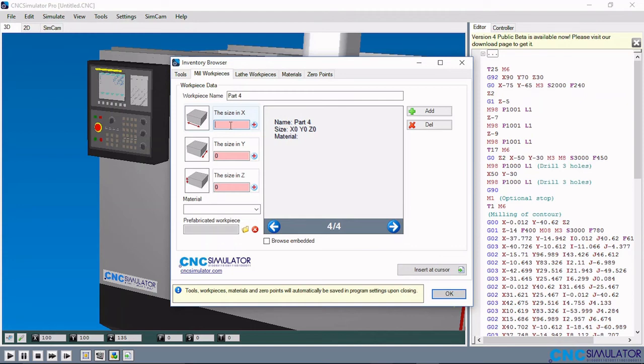So yes, here you have to specify the length of the material in the x axis. Let me say I'm putting 200 for x axis, 130 for y axis, and 5 mm for the z axis. That means the thickness of the workpiece is 5 mm, depending on whatever workpiece dimension you want to work with.